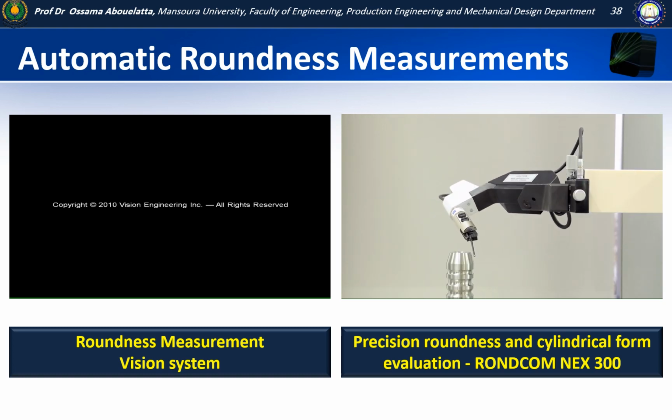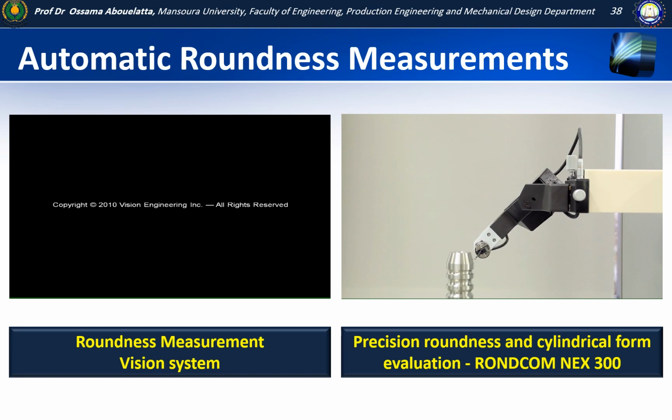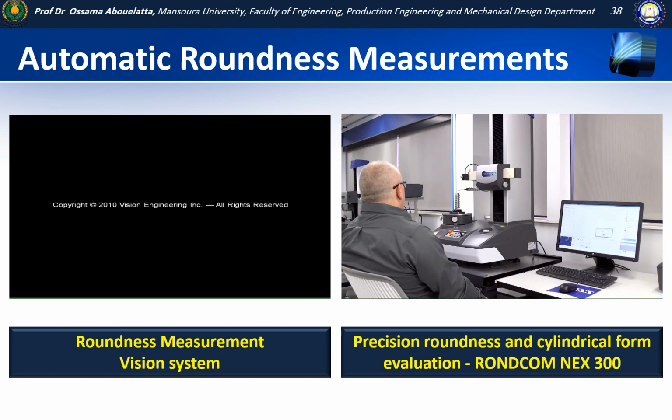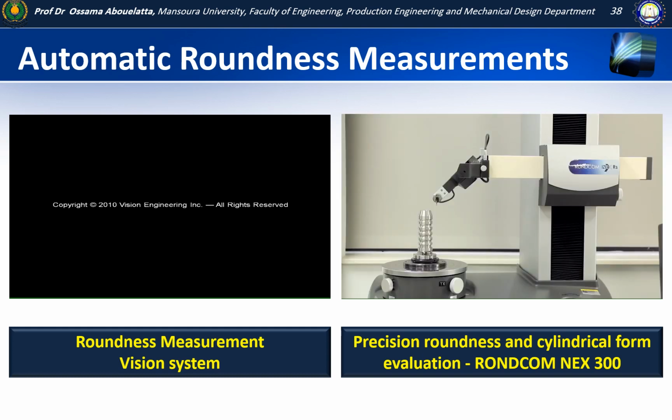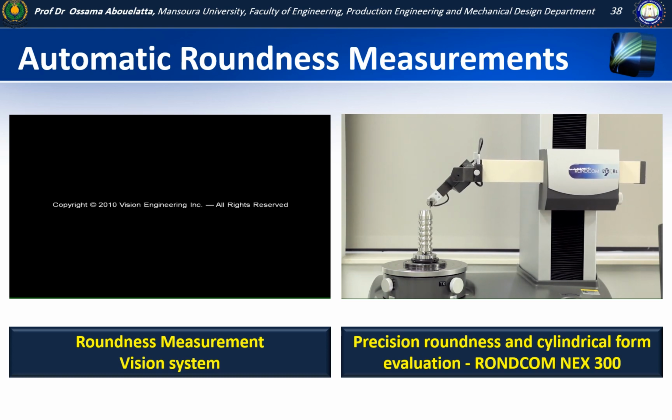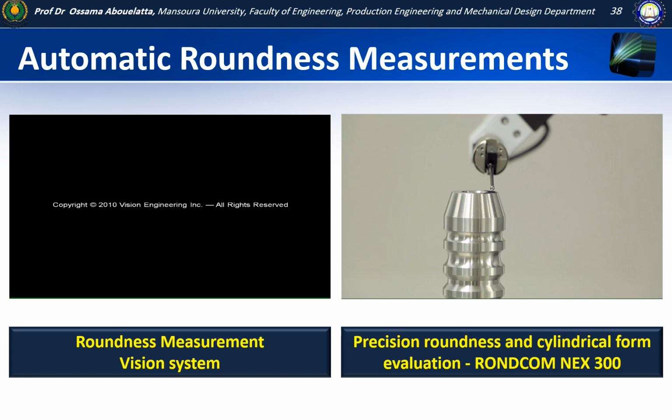From here you can see that we are able to rotate and choose a range of degrees, keeping the stylus normal to the surface. With a CNC motorized head, we're also able to measure ID, OD, upper face and lower face. So even if you only have a couple of directions, this may be a great solution for you, where your operator does not have to come back and change the direction of a probe in order to complete a measurement. It is fully programmable for multiple directions, even if it is only one or two. That way there is less operator interference and quicker measuring cycle times.